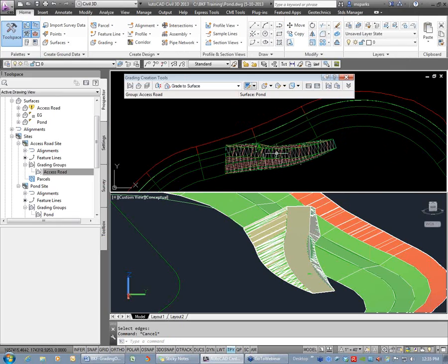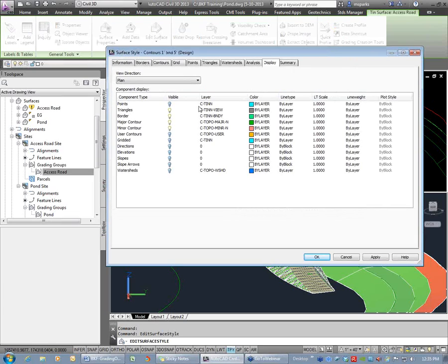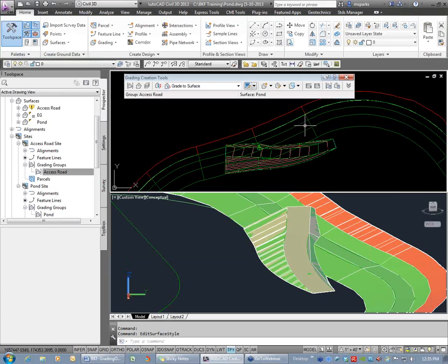On a site like this, I probably would because it's pretty small. But as I started getting a little larger, I noticed the automatic surface creation causes the computer some undue stress, it seems like. And so I have better luck when I don't automatic surface create. But a lot of times I'll try it first, and if it doesn't work, I'll have to go back and do it the other way. Okay. All right, so now I got the 2.